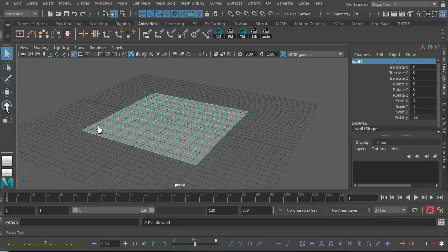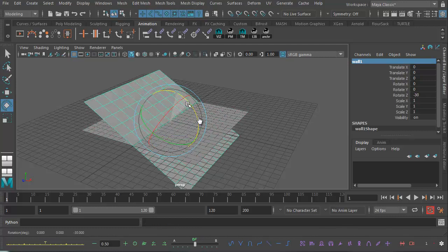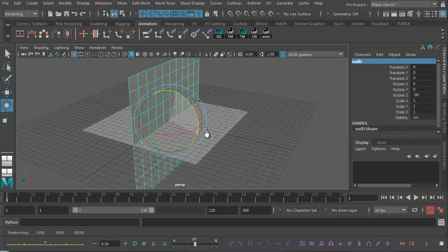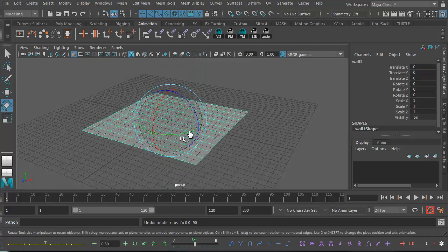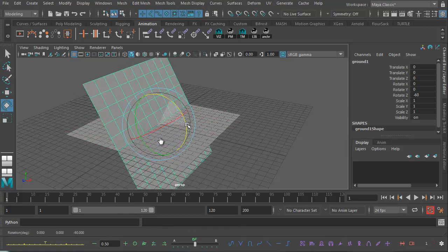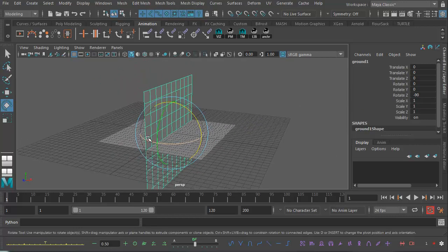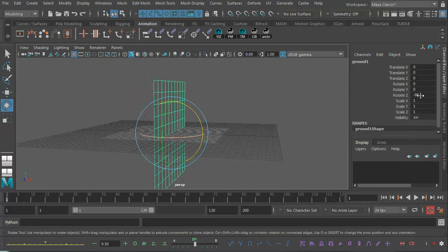So we're now going to use the rotate tool, that's this tool over here, and holding down the J key with my left hand, I'm going to drag, so I'm going to select this control here, and what the J key does is it will allow me to snap the object to the grid. So I should get now a perfect, whoops. Dear me, I have to try and do that again. There we go. Now I should have a perfect 90-degree snap. And rotate Z is -90.